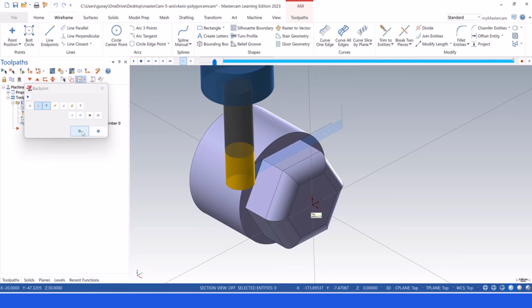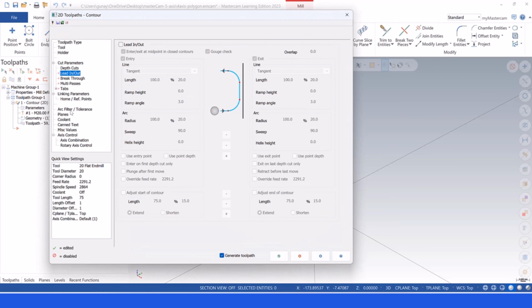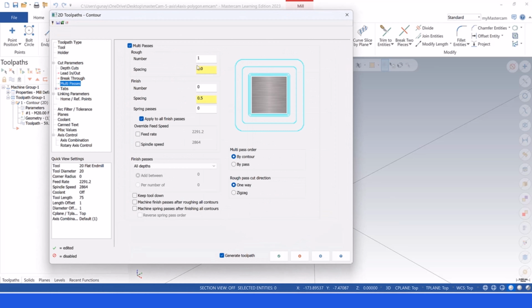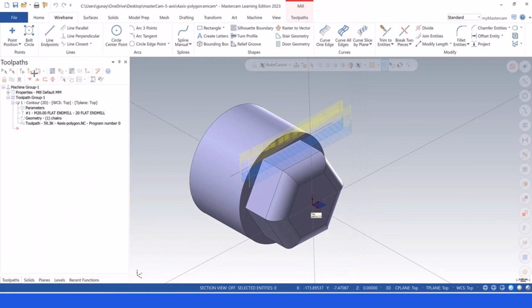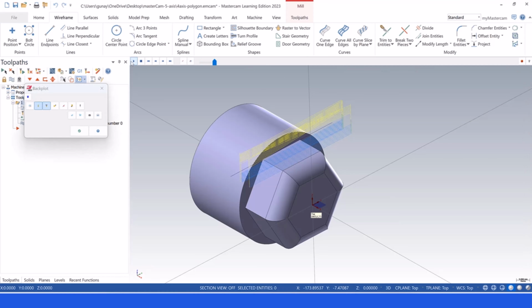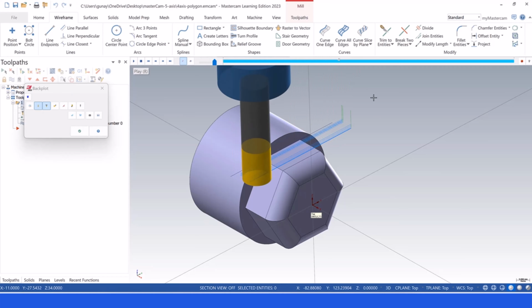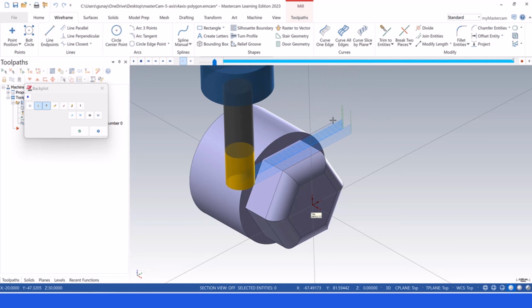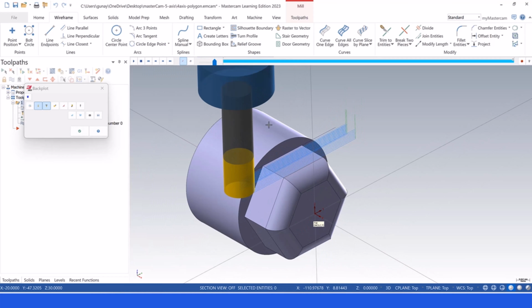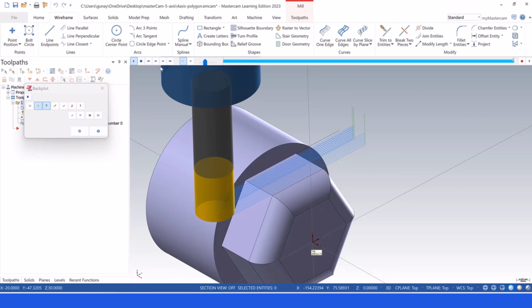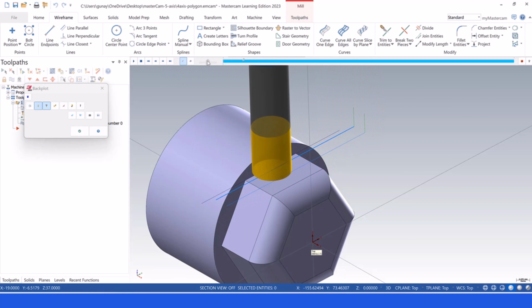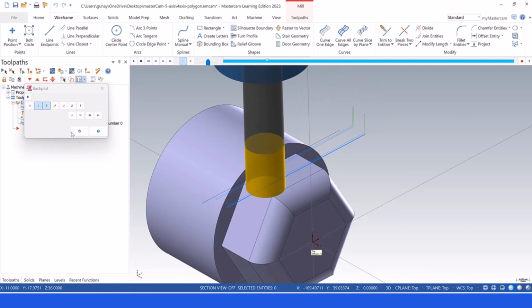Okay, it is also possible to use the multi-line options. We can turn to here and activate multi-line. I just want to see the 10 mm multi-line, and then 1, and the finish passes with 1 mm. Okay, maybe we should make them 8 mm. I don't know. And after that, let me hit here to calculate my toolpath. And after that, we're gonna start from here. You can see that this one and this one, this one and this one, and we can create that kind of toolpath actually. So we can start from here, this one and the finish one. You can see all that stuff here.